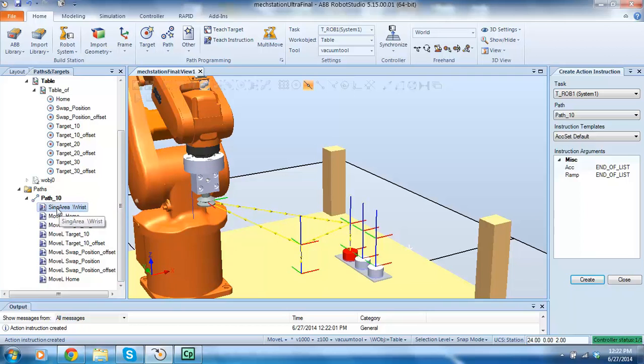Essentially what this does for us is, if there's any point along that line that the robot cannot calculate, it builds in some forgiveness. If I take away this command and try to run this, the virtual controller tries to run the robot, and sometimes it kicks out a warning or an error to say, look, one of these points along this line is too hairy, I can't calculate it. And what we're doing here is we're just building in that forgiveness. So I hope I haven't beaten that to death.